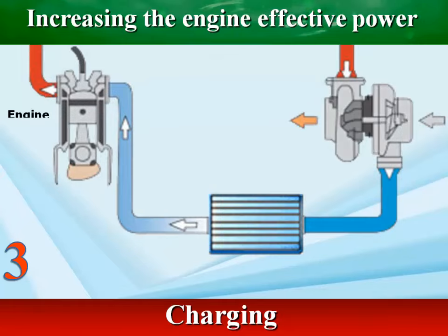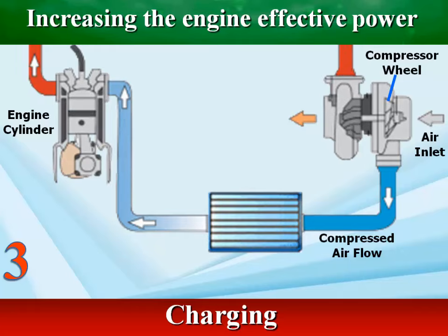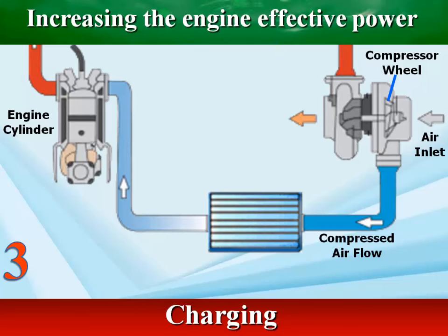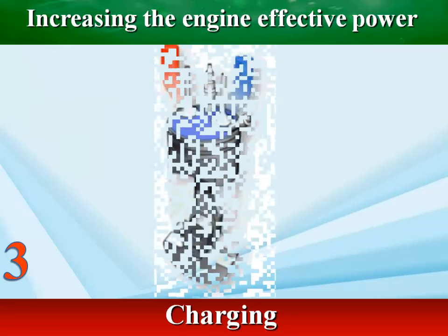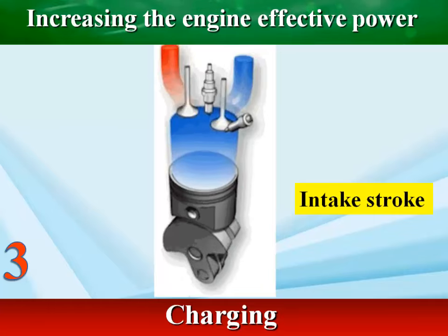The principle of charging is simple. The engine needs oxygen for combustion, which it obtains in the intake itself. More air means more power, but the delivery rate is physically limited unless a turbocharger is used to blow more air into the cylinders. With the extra oxygen, more fuel can be injected, and combustion pressure and torque rise. Charge density refers to the amount of air-fuel mixture introduced into the cylinders.